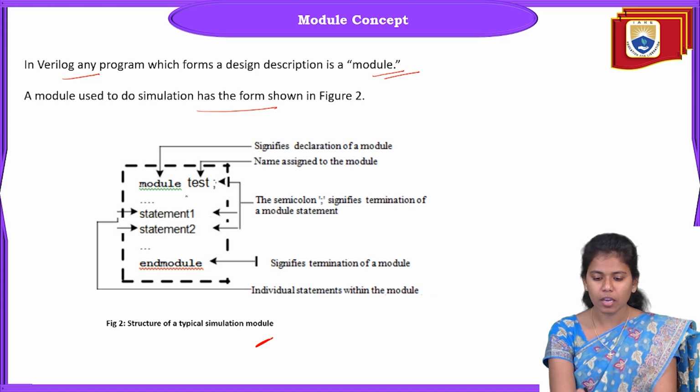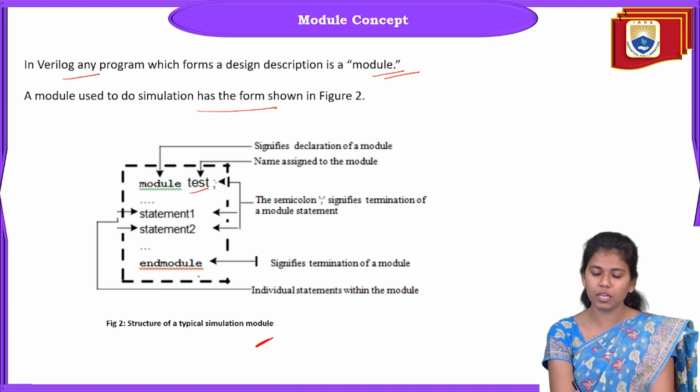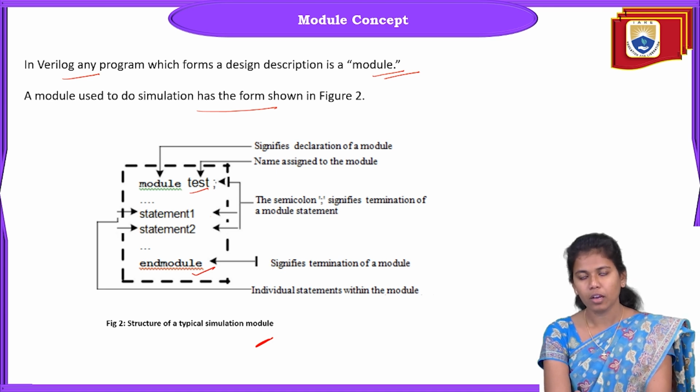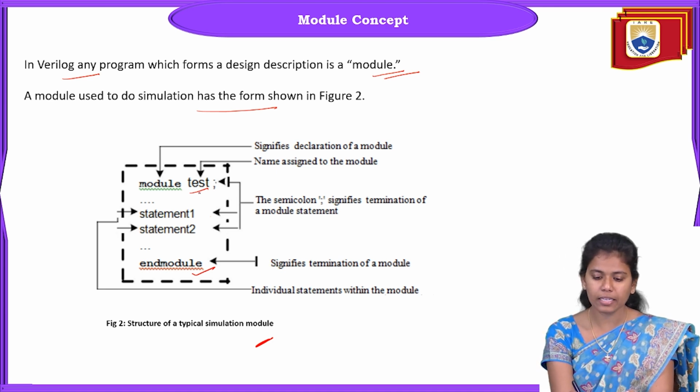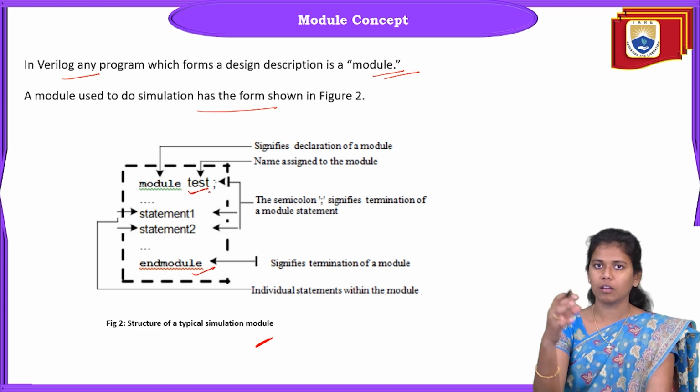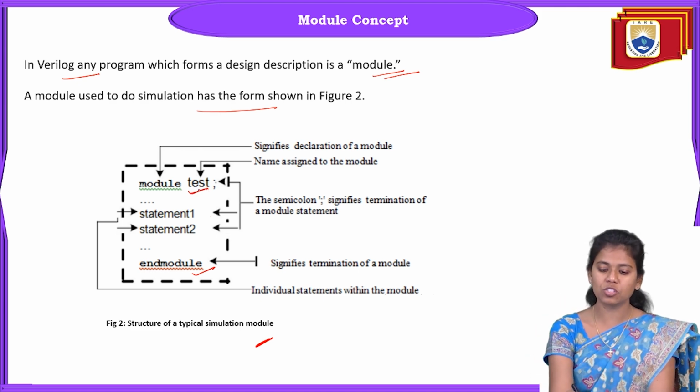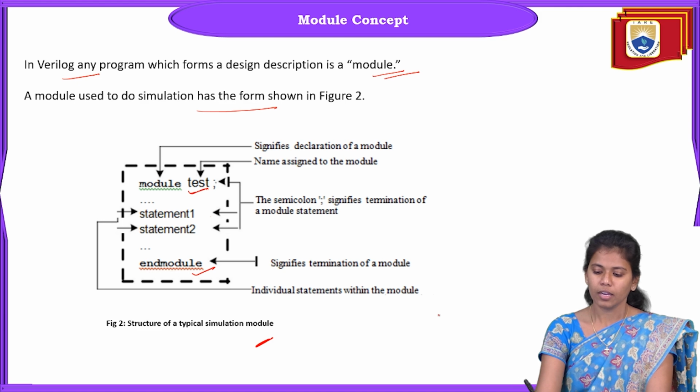So here you see a module test, some statements 1 and 2, and you end the program with endmodule. As I said, module is a keyword, and test is a particular digital circuit, a hardware circuit.